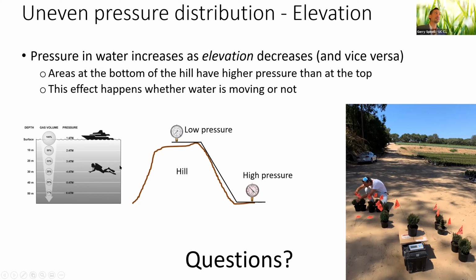And the same principle holds when you swim in the pool and you go deep and your ears hurt. That's because more pressure develops when you go deep. And the same principle holds on a pipe, and this principle holds whether water is moving or not. So if this pipe is full of water, you have high pressure down here. And if it's full of water that is moving in either direction, it doesn't matter, this principle still holds.